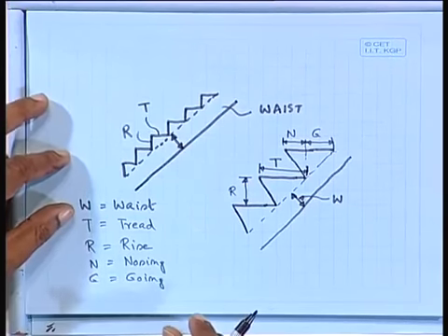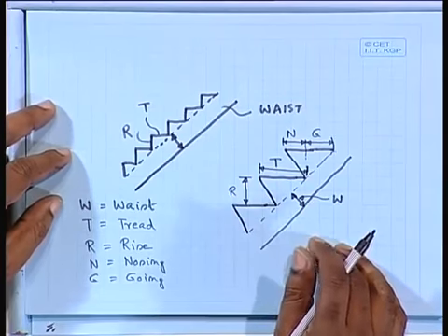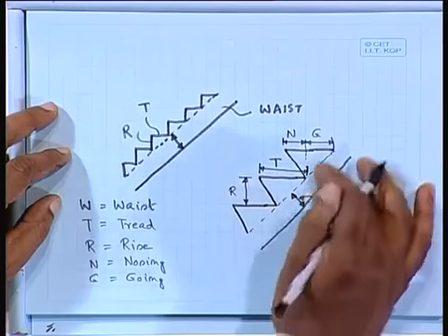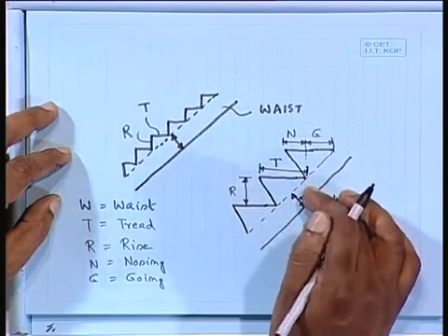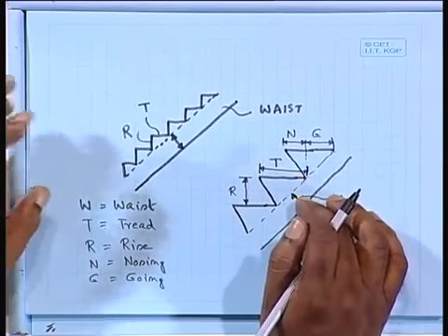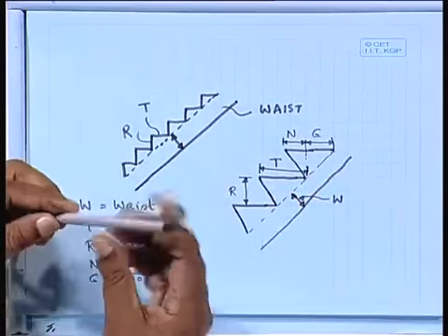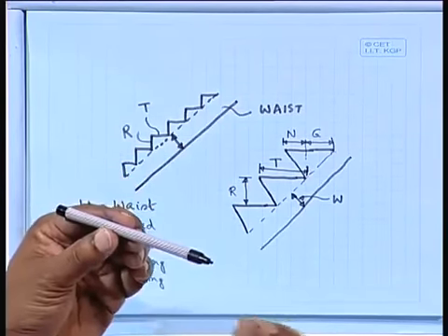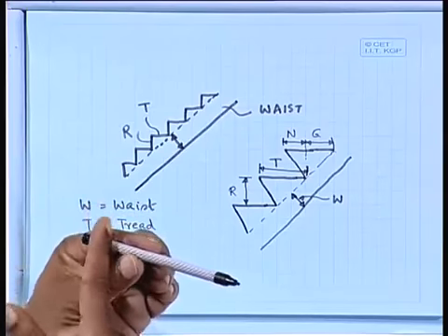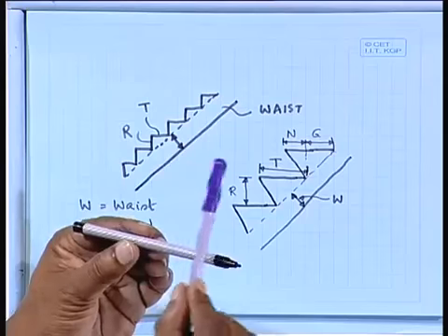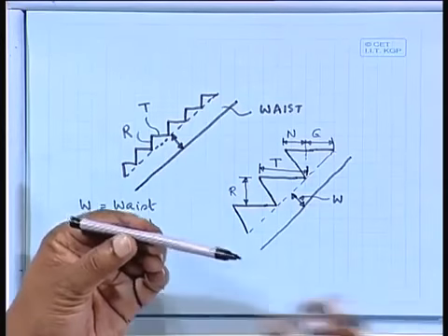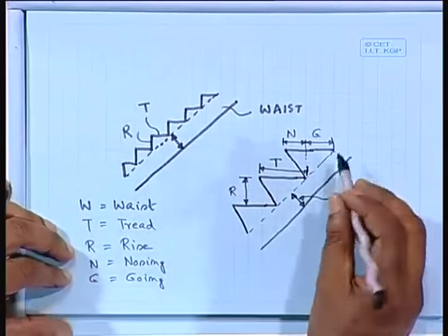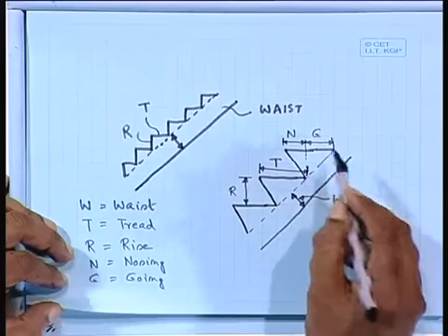So, what we are assuming here in this case, we shall take the dead load of these steps, but all the things will be supported by this waist slab. This is the most common one. The other case is if you have, say, a beam like this, and over there are steps like this. That is possible, the one I have shown you. But that design will be different compared to this one. This is the most common, popular one. So, let us see how to design this one.